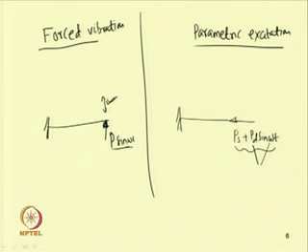load. So, if we apply only the static load to the system, it will buckle when it equals the Euler buckling load, but when a dynamic load is added to the system, it will start vibrating in a non-trivial state depending on some value of this P d and omega, that is, the amplitude and the frequency of the excitation term. So, we have to find for what values of P d and omega the system starts vibrating in a non-trivial state, or the system becomes unstable in the trivial sense.